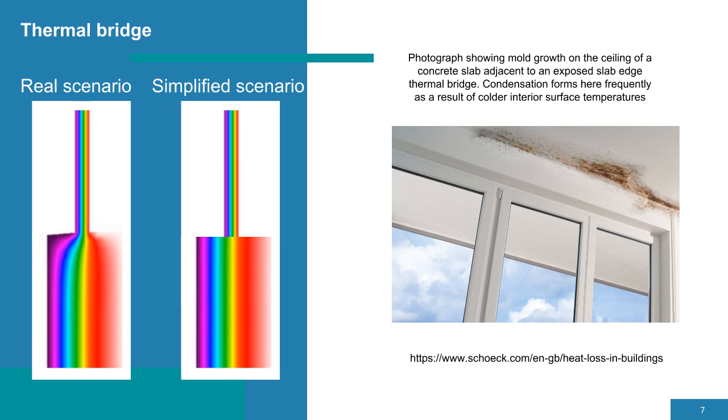The picture in the middle shows how the thermogram would look if thermal bridges were not considered. We can see that the real situation differs, so evaluating thermal bridges is important for detailed calculations. There is also another benefit for civil engineers from thermal bridge analysis.